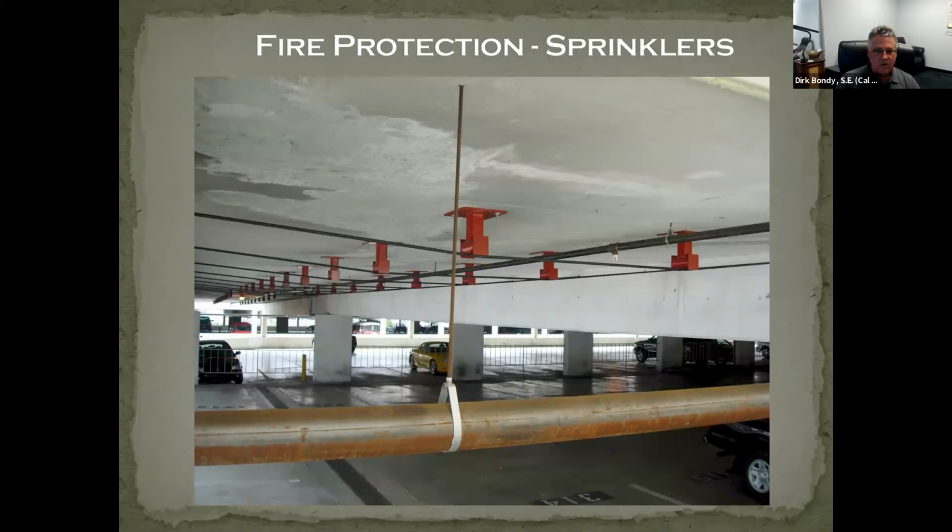So that's one of those situations where you've got to sit down, be confident in what you're doing, and offer a different solution. Now, this technically probably doesn't satisfy the fireproofing requirements, but everybody horse traded and got what they wanted in a strengthened structure. And most of the strengthening is voluntary. You have to understand there's very few things that will mandate that the building be fixed. Most strengthening is always voluntary. So we start with that, and we even put that on our drawings, voluntary strengthening. So that kind of leads you to believe you can do whatever you like, but building departments don't always see it that way.